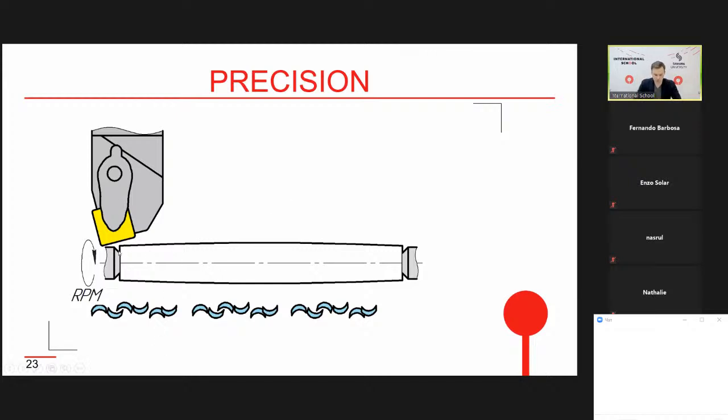Of course here you can see that the shape is not a cylinder, but it's a magnified picture with magnified error. I especially made this picture with zoomed error. But really, after this type of machining, we will see a cylinder. But when we use a special measuring technique, we will see that diameters differ in different sections.